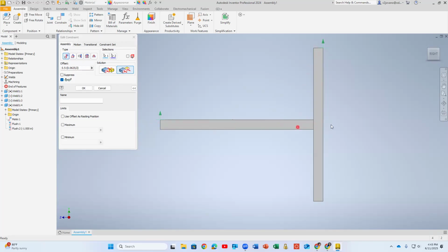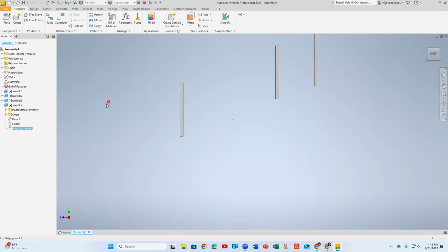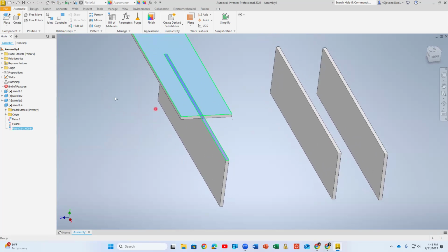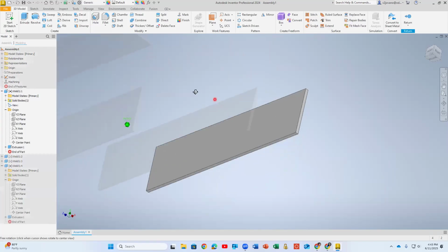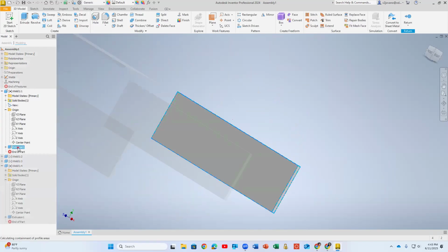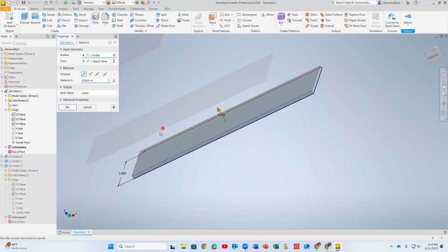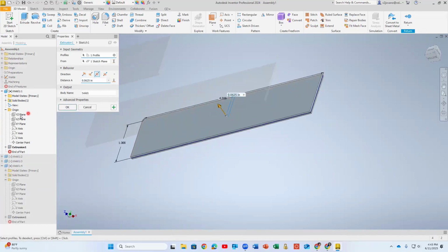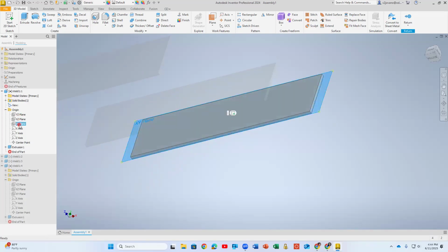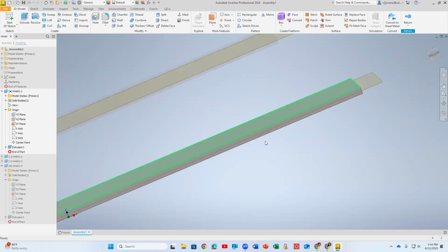I didn't say the middle one. You know, if I had, this is one way, okay, I can cancel this. I don't need to. I can just show you the last one from the beginning. So for example, if you made your weld, if I go back to the first weld we made, and we see how we extruded this, basically, if I switch my extrusion to symmetrical, that means my plane will be in the middle, the plane in which I draw this, which was the XY plane. So you see, one way is to actually do this. It's way more simple than doing this crazy equation.